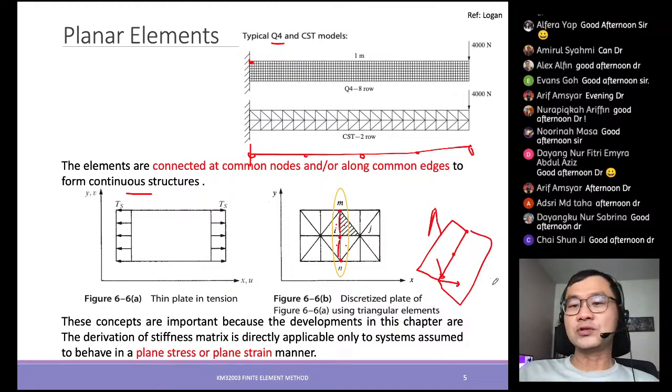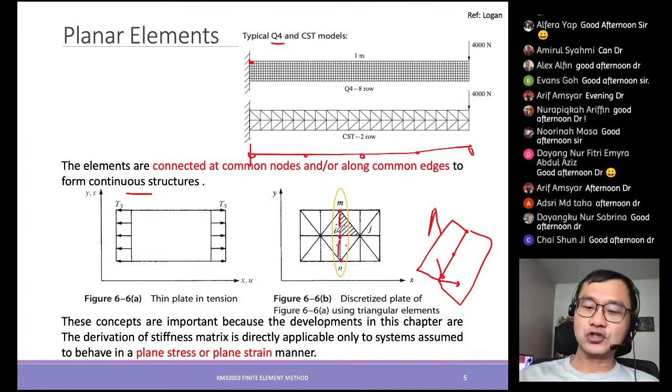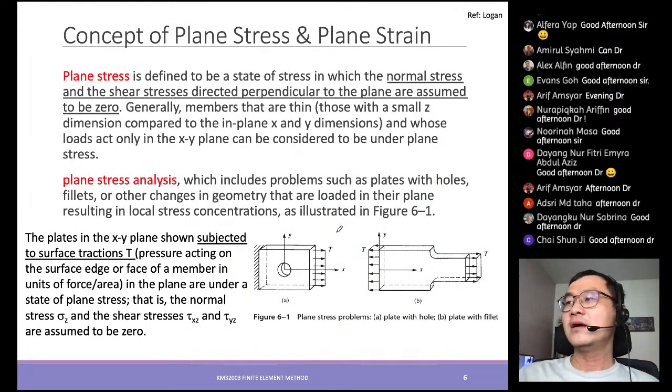So these are those kinds of considerations, discretization problems or meshing problems, when you deal with three-dimensional models, or when you deal with finite element analysis. So besides selection of the elements, the meshing and the merging of all the relevant nodes to make sure they are common are very important for the software to solve it. Or else you may either get a very strange result, or the software may show you some type of error, like a discontinuity error and so on, which it may not be able to solve later on.